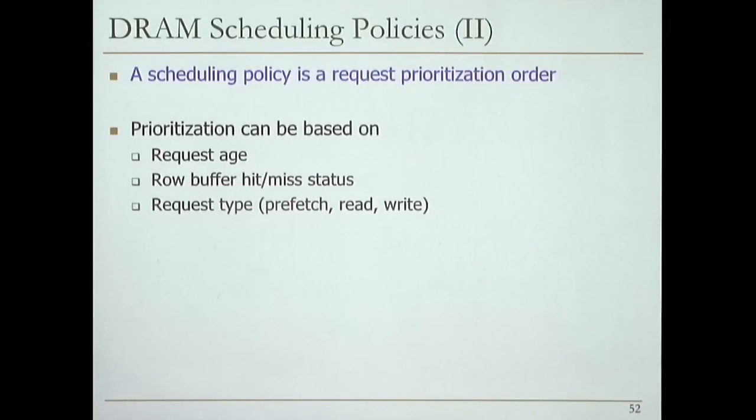Because if the requests are coming from write-backs from your last level cache, the only write requests you're seeing would be those write-backs, evictions. But then in modern processors, you actually have uncacheable accesses also. You could actually directly write to memory, bypassing the caches. So you may actually see true write requests, not evictions. So requester type is the load miss or store miss. This is important, right? Maybe load misses are more important, whereas for a store miss, you're just going to write the data over there in the cache.